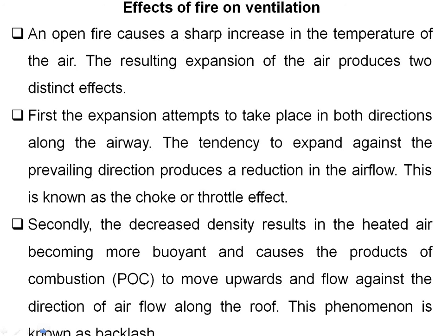Secondly, the decreased density results in the heated air becoming more buoyant, and this causes the products of combustion, POC, to move upwards and flow against the direction of the airflow along the roof. So the products of combustion is the most important term I have used here, that the decreased density makes the heated air more buoyant, and this causes the products of combustion to move upwards and flow against the direction of the airflow. This phenomenon is also known as backlayering. I told in the first slide what direct blast and backlayering are.